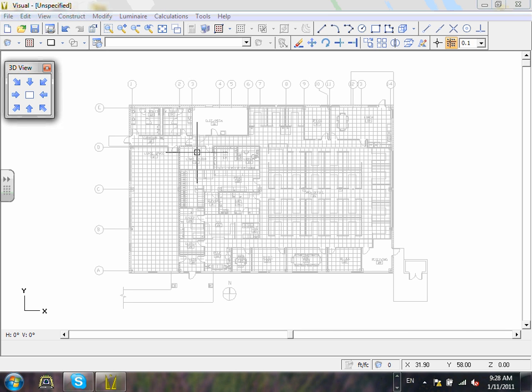We brought the background. The second step, guys, is solids. I want to bring your attention to a few things. In the CAD, if you have a recessed ceiling, I believe the recessed ceiling that we have right now is sitting at 10 feet. If you have a recessed ceiling, set your calculation at 10 feet. We changed this one over time, but you can put it at 9 feet. Let's just standardize at 10 feet. Every place where you have a recessed ceiling, let's make it 10 feet.